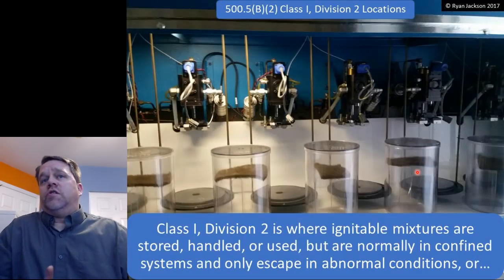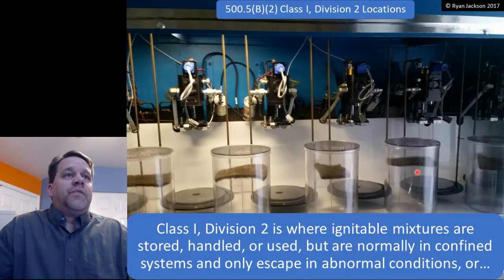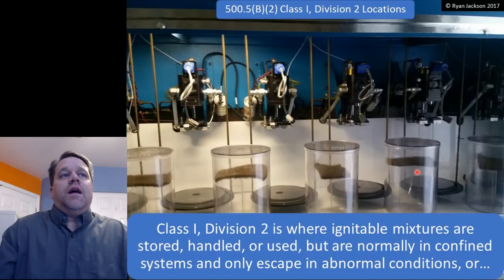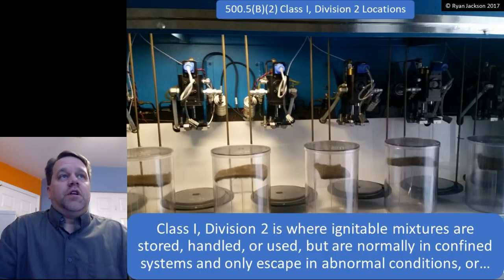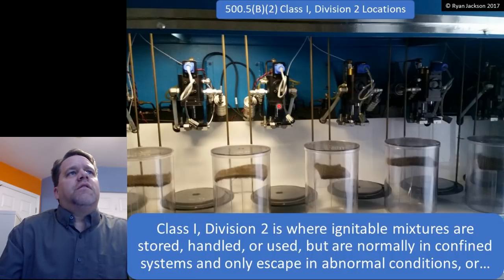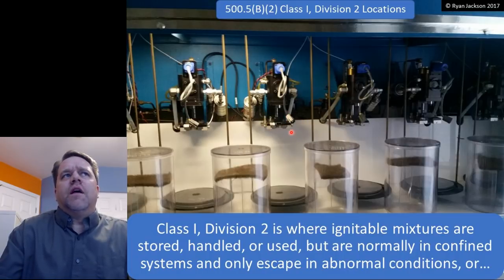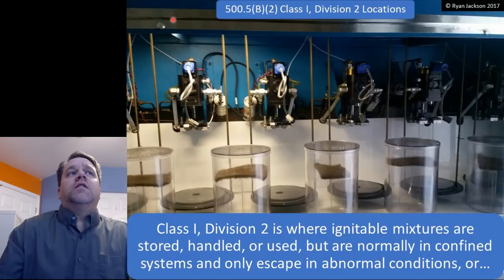Compare that to a Class 1 Division 2 location, which is significantly less hazardous. Class 1 Division 2 location is where ignitable mixtures are stored, handled, or used, but are normally in confined systems and only escape in abnormal conditions. It's hard to see from this photograph here, but let me explain what's happening. Inside of here, they have some fuel injectors, and they're testing them, so they're spraying gasoline vapors. But this entire cabinet, can you see right here where my pointer is? That whole thing is covered in plexiglass. So it's inside of that unit.